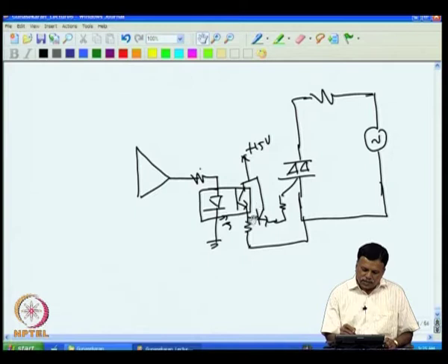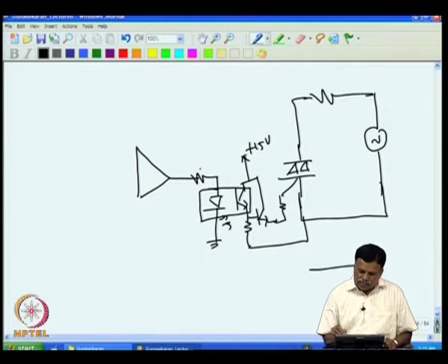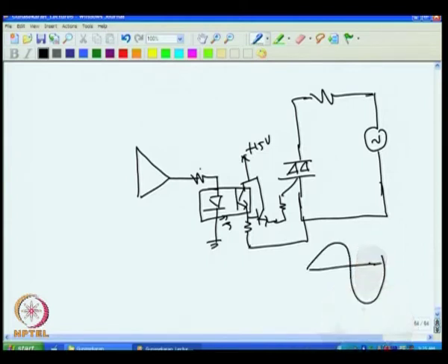That is in the sense that now it is firing randomly, that is when it comes high immediately it is fired, but the firing need not be coinciding with the zero crossing of this AC. If the AC cycle is like this, if I fire at this point, automatically it goes off at this point. Next cycle, since voltage is present, it is firing again like this and it goes. Suppose if the gate signal comes high at this point, then you will be firing and suddenly large current will be flowing, that produces electromagnetic interference.